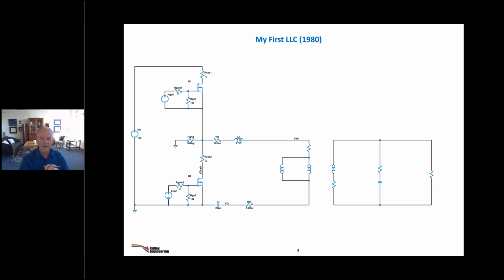So that was an incredible nonlinearity in the system. And the unique thing about this converter was that it would provide regulated AC output with no feedback around it. So as the input line moved up and down, the output would always regulate the AC output. And that's the characteristics of ferroresonant converters.